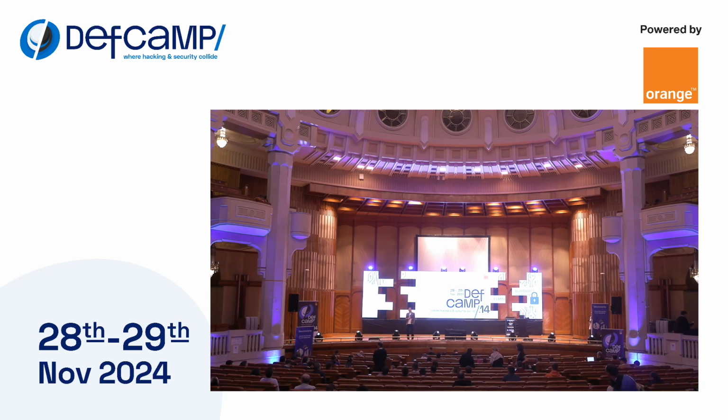Thank you for the presentation. Can any of your devices act as, let's say, a command sanitizer between an engineering workstation and the PLC? So if I'm issuing some commands, I need to put some parameters there. And the machine accepts from 0 to 200, but I know that 100 is very dangerous. But I'm still typing, instead of typing 10, I'm typing 100. Is any of your devices able to send a message or block the command and tell me, you are doing a bad thing?